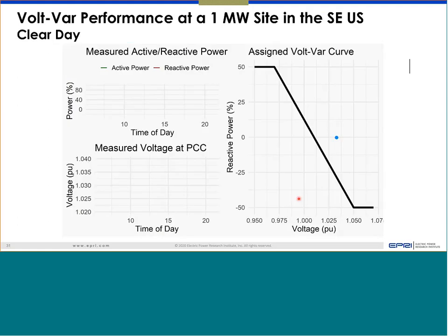Here I'll show an actual video. It's measurement data, all real field data. We just put it into a video format to see what happens in a whole day from sunrise to sunset: power change, reactive power change. You will see the voltage variation throughout the day.